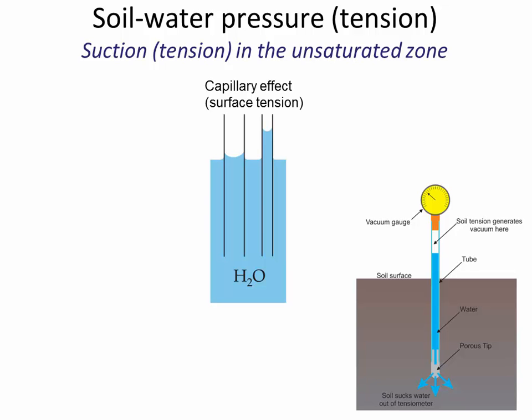And so there is this device, the tensiometer, as it's called. You jam it down into the soil carefully so that you don't disturb the soil. There is moisture inside of this tube, and the soil will start drawing the moisture down out of the tube, but it creates a vacuum above it.